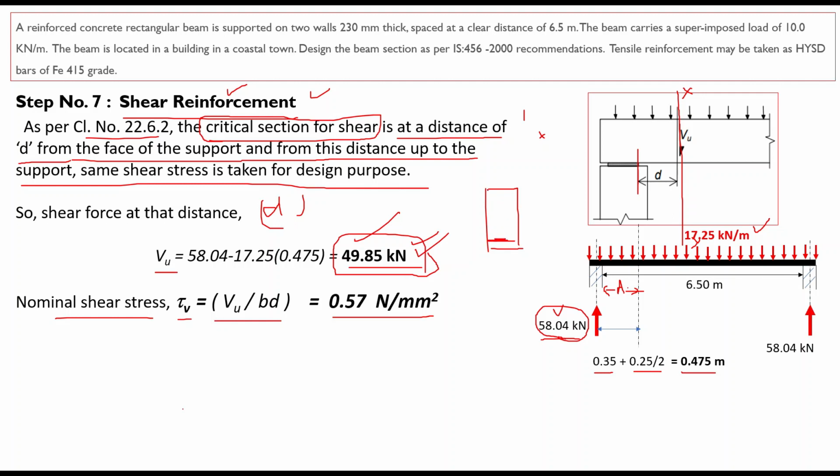So concrete is very good in compression, and it also has some capacity to take care of the shear forces. Now we have to refer to the IS code guidelines, and to work them out, first of all we have to understand what is the percentage Ast we have provided, that means the percentage of steel which we have provided at the support level.